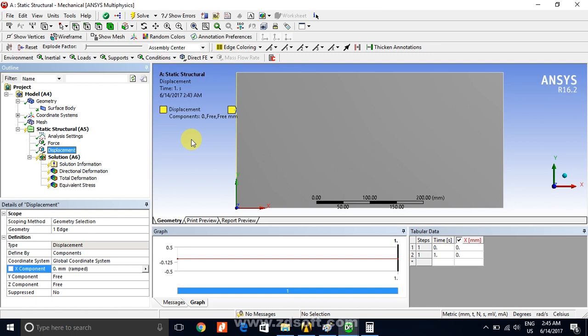So in the opposite way you can think, when the reaction force is coming in this direction, we must apply the displacement boundary condition in this direction. When the force is not coming in the other direction, then why would we apply this boundary condition in the y direction? As per mechanics, we know that if any body is pulled in the uniaxial direction, the reaction force would be on the same axis. The reaction force could not come perpendicular to that, because the force is applied simply along the axis, and the reaction would be in this direction.